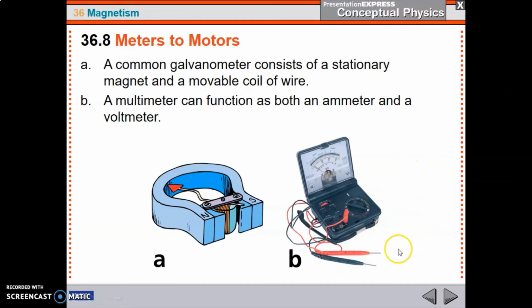So I don't need you to understand how this works. But here I've got a magnet around it, and there's a loop of wire, loops of wire, and this is on a pin that can rotate, so this cylinder can swing around. So when you put current through those wires, through the coils, you're going to make a field, and that field is going to interact with the permanent magnet. The more current, the more the field bends, and the more the needle moves. Does that make sense? Great.